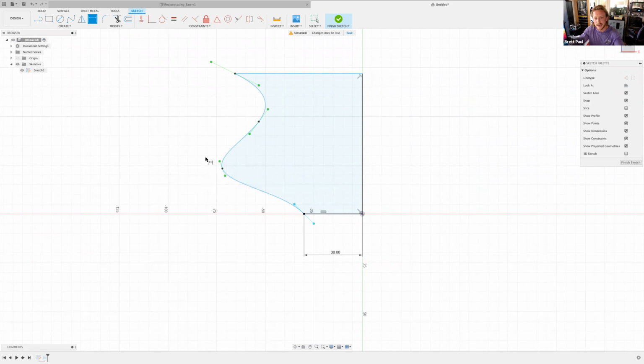So I have not successfully been able to go back and adjust the overall width of the vase while maintaining the outer curve that I wanted. If instead I had defined this spline, which we'll do right now, we can come back to it and change specific parts of it without compromising the rest of the sketch or the rest of the design.